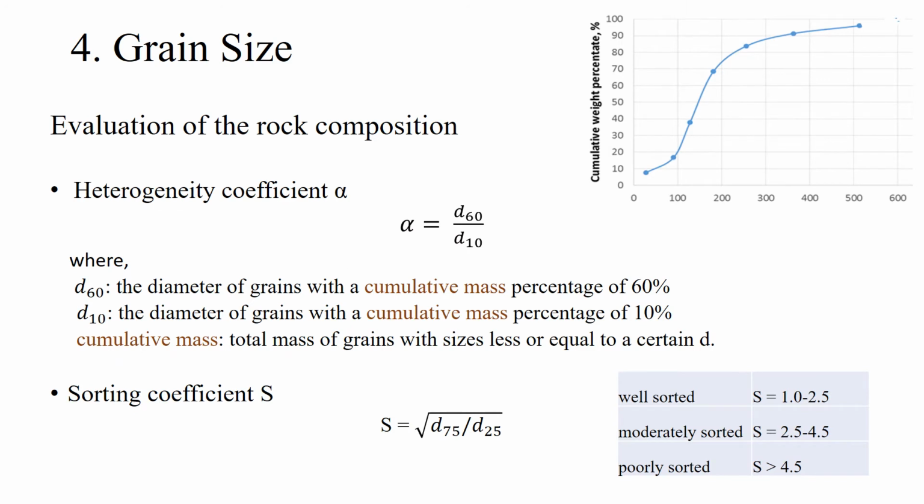So once it is done, you can measure the weight of each sieve and figure out what the weight of each mineral group. And then you can plot the figures that we see on the right. So we have the sizes down there and we have the weight percentage on the y-axis. And when we do that, this is actually cumulative weight percent.